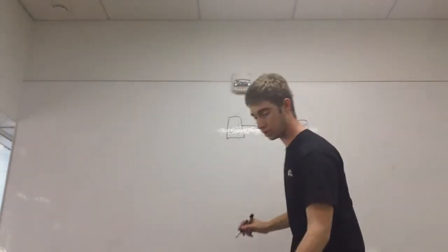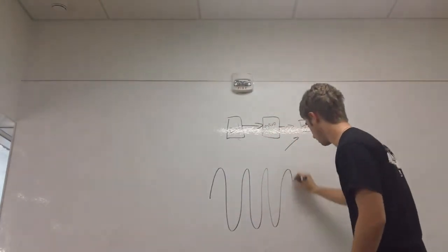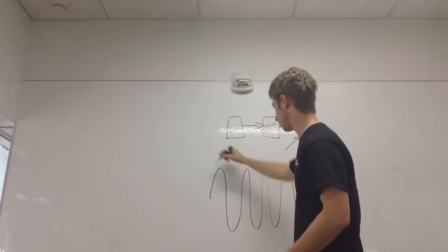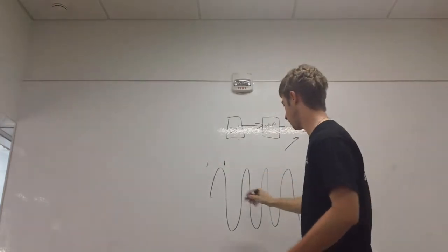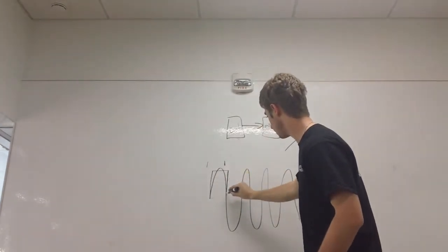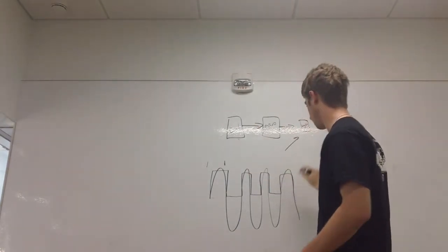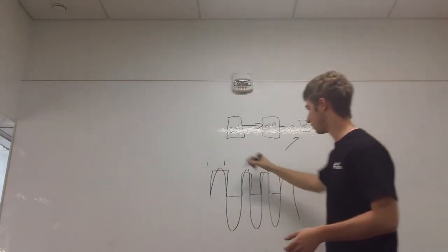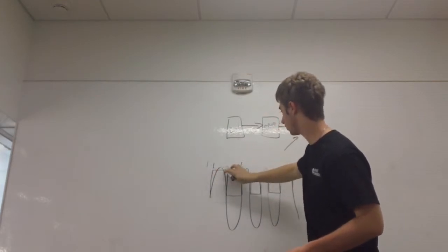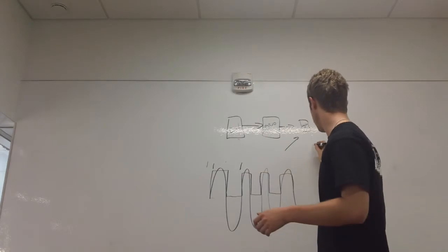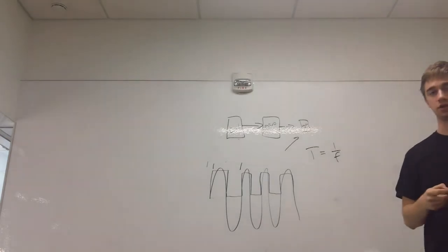Okay? So essentially what I'm going to be doing is you'll have a voltage signal, and this will be going very fast. I mean this step will be maybe several microseconds. Okay? And what I'm going to do is convert this to a square digital wave. And that's how the Arduino is going to read how fast this frequency is. Okay? So it's actually going to measure the period. So it'll measure how long this length is, convert the period, which T is 1 over F, to frequency, and then we'll use that first equation I showed you.